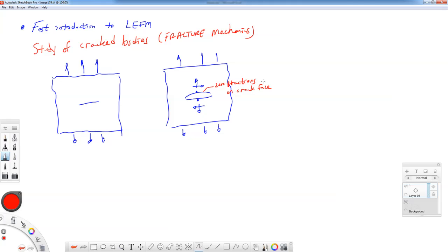Now if you have a crack that closes, well then those surfaces can contact, and then you can transmit some stresses. Then the solution for the field would generally be like you had an uncracked body. What we're going to do in Abaqus to start off with is just model a cracked plate, but we're going to look at a biaxially loaded plate, because that goes along with our Westergaard solution.